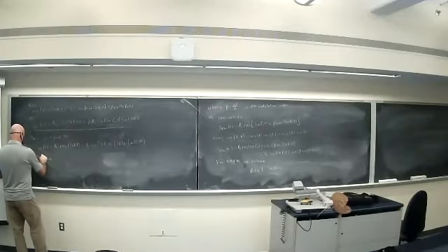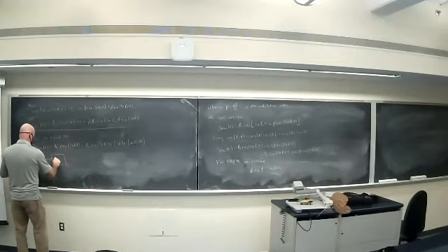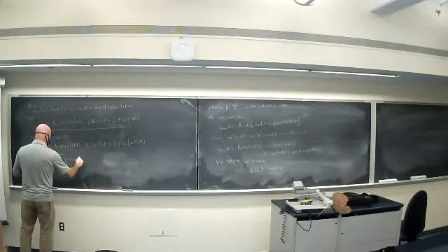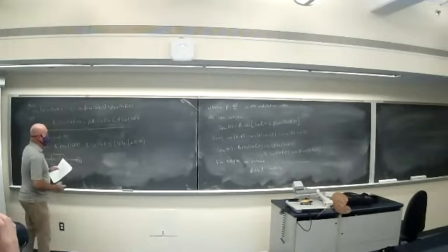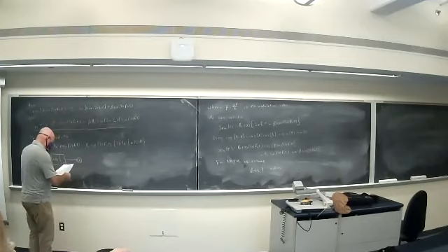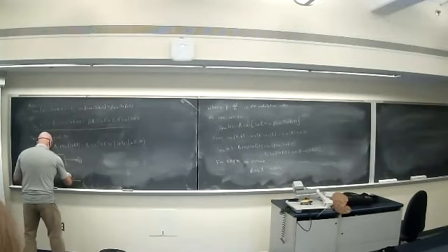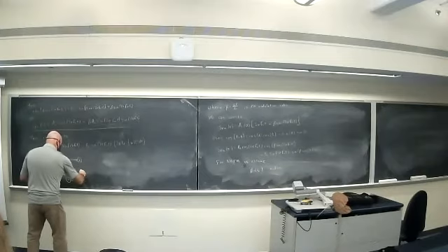So we have our message coming in. We multiply by 2 pi kf and integrate. Okay. That would actually generate this term. We multiply by sine. Okay, so actually I have a generator here that generates a cosine 2 pi fc t, and I shift that cosine by 90 degrees.